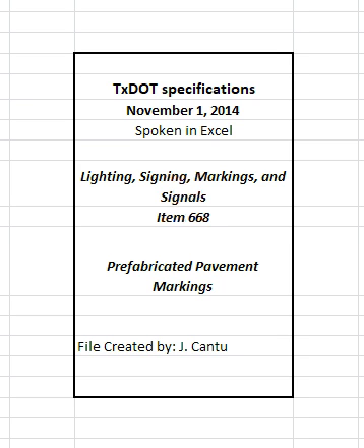3.7 Performance period. All markings must meet the requirements of this item for at least 30 calendar days after installation. Remove and replace all pavement markings that fail to meet requirements at the contractor's expense unless otherwise directed. Replace failing markings within 30 days of notification. All replacement markings must also meet all requirements of this item for a minimum of 30 calendar days after installation.